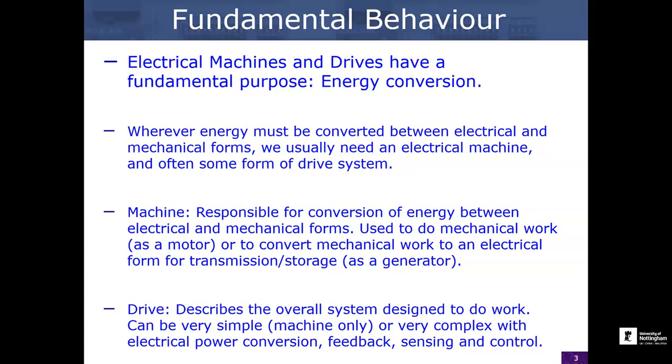Then the definition of a drive is something that is the overall system designed to do the work. So drive is a sort of catch-all term for an overall system. That can often include the motor, but it could include any power electronics, any control systems. Confusingly, occasionally people will call a power electronic drive, as in just the power electronic converter, the drive as well. There's a lot of interesting terminology in our field. But ultimately a drive is a system designed to do a job.